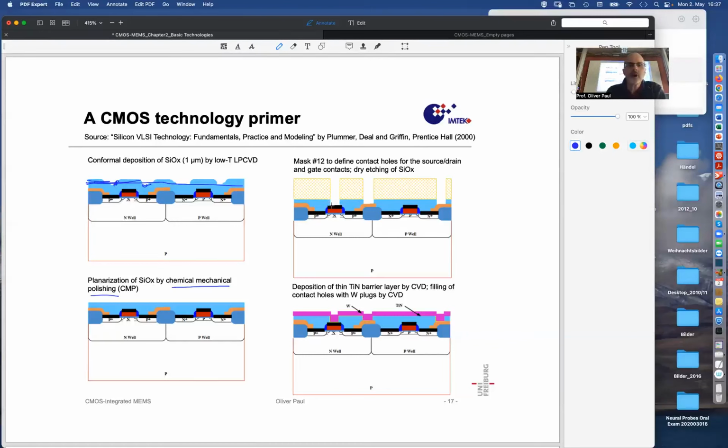And now we have opened the oxide over the gate. Now, usually that is not done over the transistor, okay? That is done somewhat on the side. The transistor area, the active area of the transistor, is well delimited, a rectangle, and the gate protrudes over the field oxide in that active area, and that's where actually the contact is done. You don't want to ruin your precious transistor. You leave that alone.